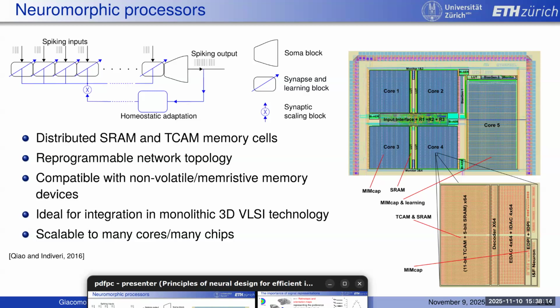That's why the TrueNorth chip was so big, because every neuron, or every core in their case, takes up physical area. And when you fabricate chips, area is what matters. You pay by the amount of area in silicon. And so this type of technology doesn't scale very well if you want to do very large networks. It's good for relatively small networks. This is like 1,000 neurons. Maybe now with more advanced processes, you could do 10,000 neurons, but definitely not the size of a ChatGPT network.